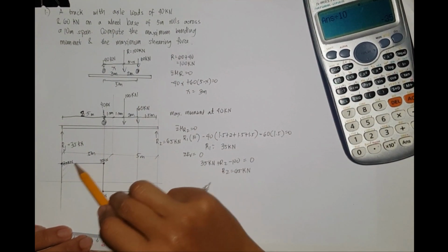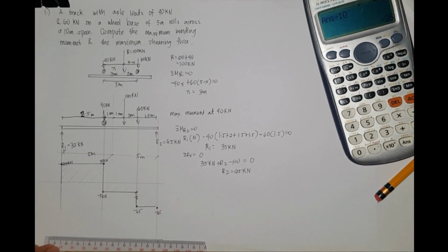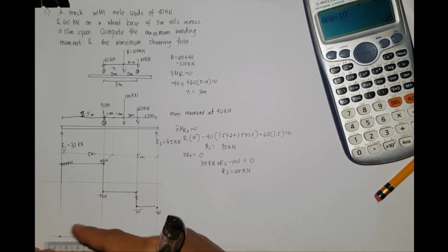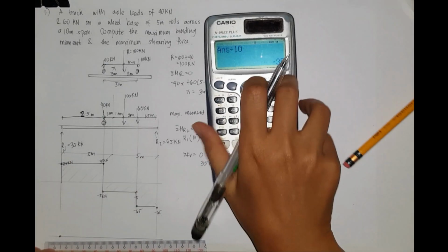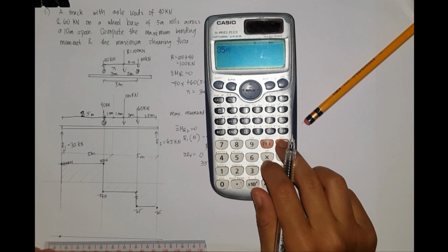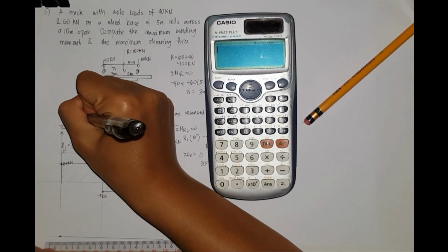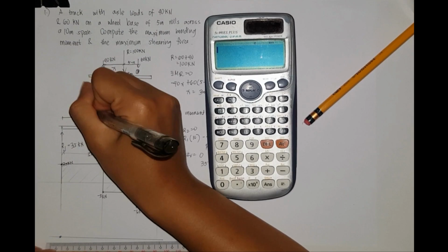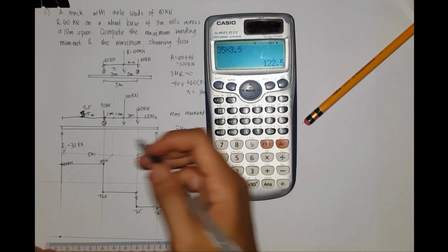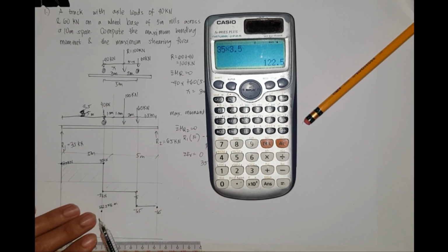And to draw the moment diagram, we have here. So do we have a moment at this part? So wala, 0. Do we have an area in the shear diagram? We have, which is equal to 35 multiplied by, this must be 3.5, not 2.5. So 5 minus 1.5, so we have 3.5 here. So we have 35 multiplied by 3.5, so we have 122.5 kilonewton dot meter.